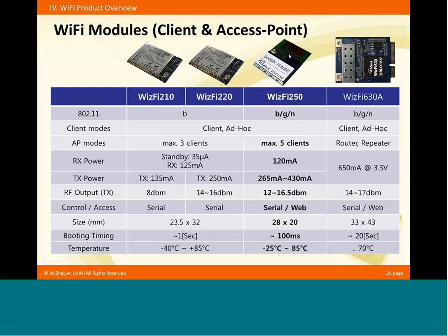But if you access, for example, with a smartphone, you can access the internal web page, you can configure that, or you can access the serial through Ethernet to serial, of course, access serial data, and you have your application. So up to 5 clients can connect to the module, maybe doing something on the module's internal web page, and one of them can access the serial interface and make serial to Ethernet.